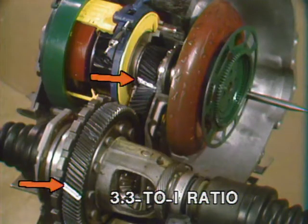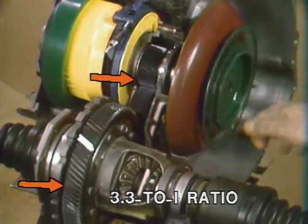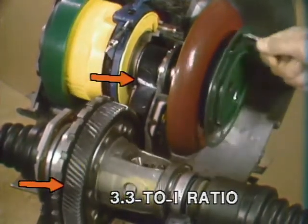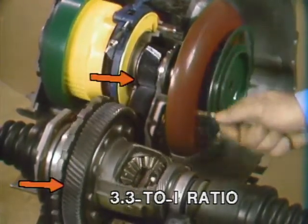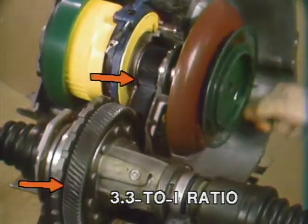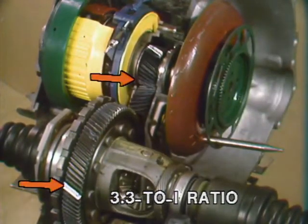Now follow these marks on the input and output gears as we demonstrate the final drive gear ratio, which corresponds to the rear axle ratio on rear drive cars. Count the turns of the input gear. 1, 2, 3, and 1/3 to 1 revolution of the final drive output gear. The final drive has a 3.3 to 1 ratio.